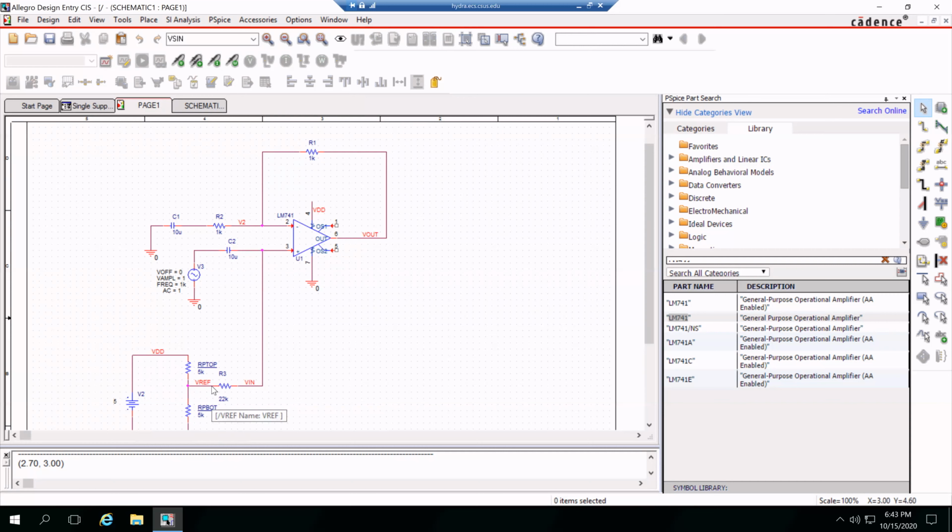So remember, they're going to ask you at what frequency does C2's impedance equal the impedance seen looking down? So that equation is going to be very similar to the one up top. It's going to be 1 over 2 pi C2, so 1 over 2 pi, 10 microfarads, equals this impedance looking down, right? So the impedance looking down, there's 2 impedances that you could work off of, right? You could work off of the minimum or the maximum. Which one do you want to choose?